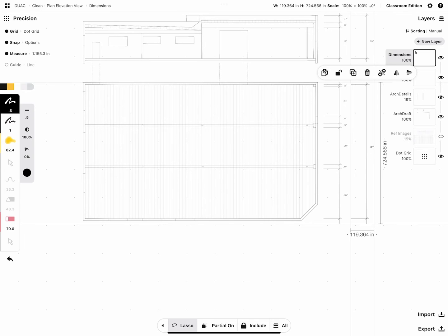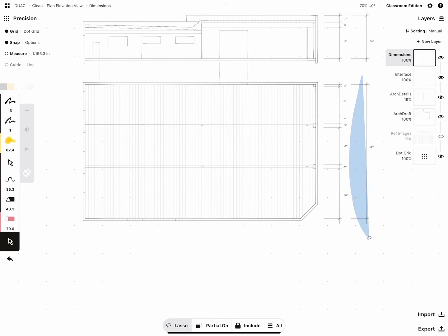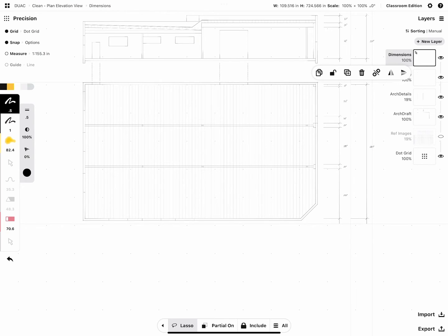First, I want to have snapping turned on, because with the snapping, it snaps to the grid in everything. So when I do a copy of this, now I have to rotate it. So I made a copy, I'll duplicate it, and then here at the bottom, I go to scale off, rotate, very good. Now with two fingers, I rotate it and move this over to here. And then at one point, it will snap to be horizontal.